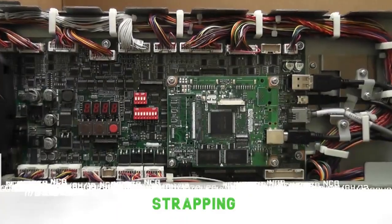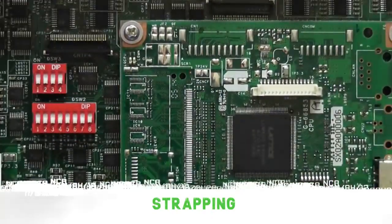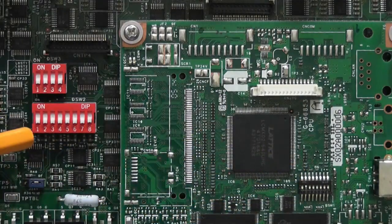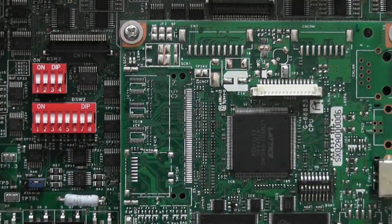There are 3 dip switches on the upper main control board. The only switch that should be in the on position is the second one on DSW1, the black set of switches to the right. All other switches should remain in the off position.